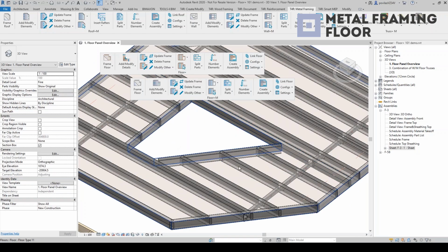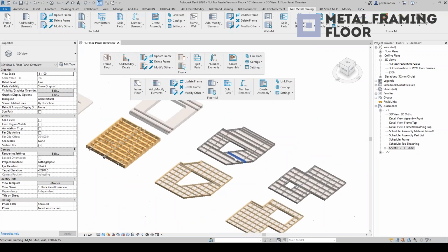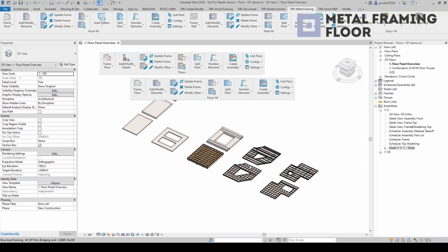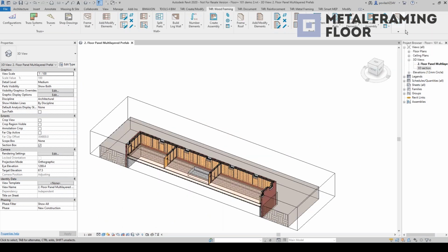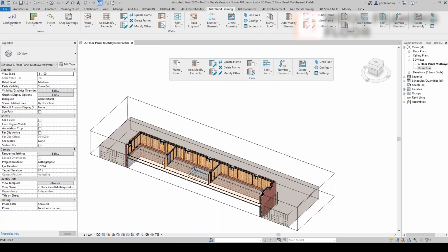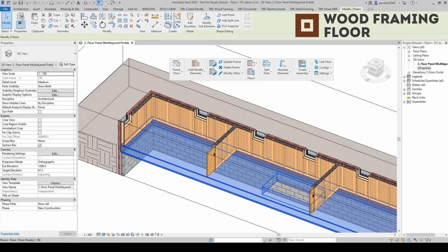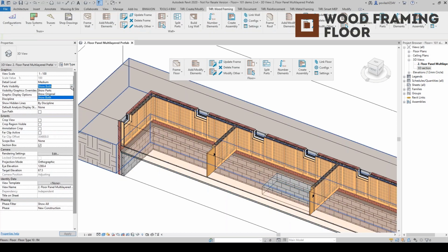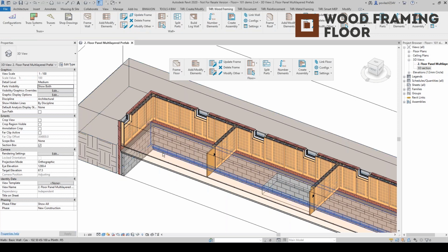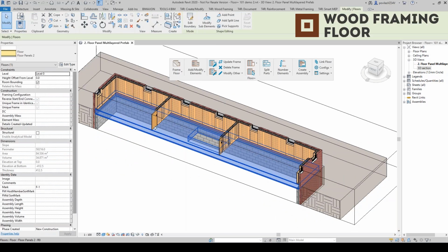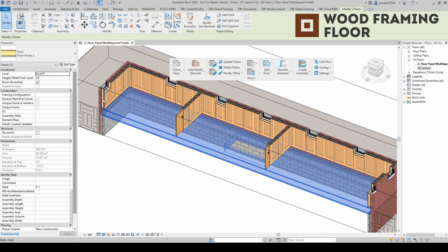Okay, right. So let's now see how we can split the entire floor into multiple panels for prefabricated construction type. So again, let's just switch to both. Right, so my Revit floor is in place. I have a bit more context. Walls are framed, inner and outer leaves, and there's a basement going on as well. Okay, so select the floor and go to view to split parts.